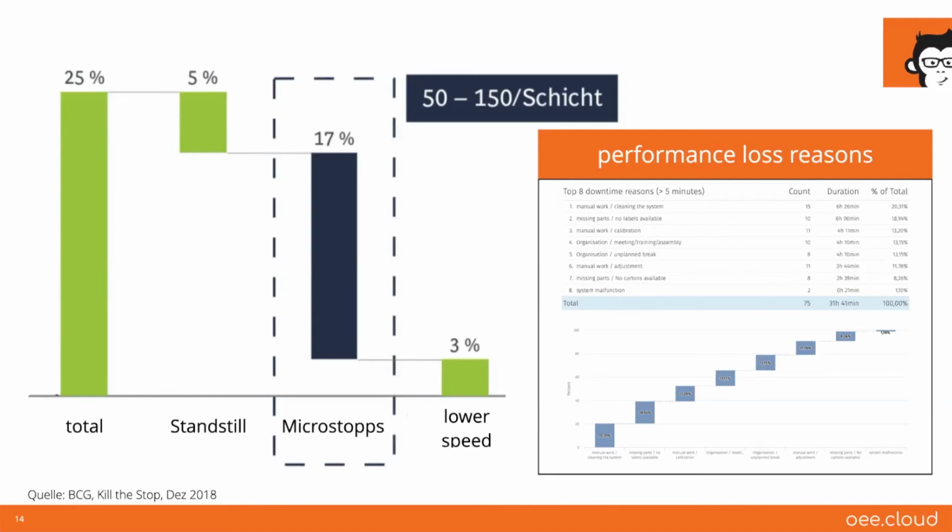Most of the time, this is not the case. Running it faster does not give you more microstops. Microstops are usually a problem with adjustment of the machines. If the adjustments are not precise enough, you increase the microstoppages, which are the small stops between a minute and 2 minutes.